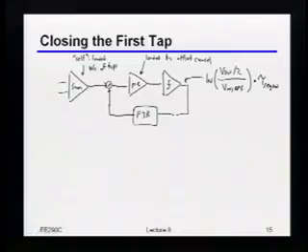And by the way, you're not even actually done, because now, even in this FIR filter for that very first tap, I've got these digital swings that I'm trying to feed back into those switches that I'm generally trying to keep in SAT. So I might actually need to put some either buffers or level shifters or something like that, just to make sure that my analog summing nodes are still behaving the way I want them to. Okay? So that's not to say that this whole thing is impossible to actually close. You can indeed do it. But it tends to be pretty tight.